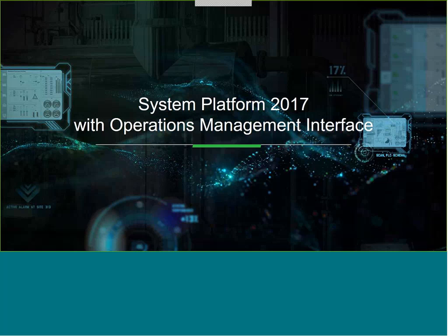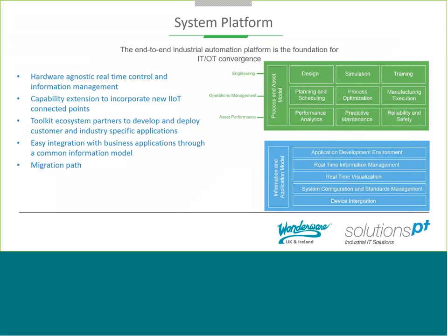Then if we just move into System Platform, and you've probably heard us talk an awful lot about System Platform in the past, for those of you that aren't aware, this is more of an enterprise-level SCADA. We're still very much, as a Wonderware house, hardware agnostic, so we communicate to anything, anywhere. This certainly extends our capabilities in terms of IoT because we can connect to things like these small sensor type devices and get data into a centralized SCADA solution and do whatever we want with that data.